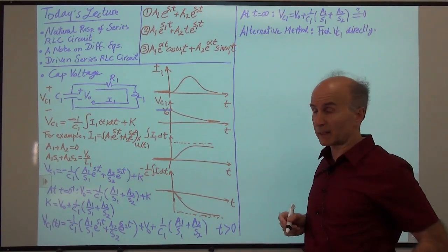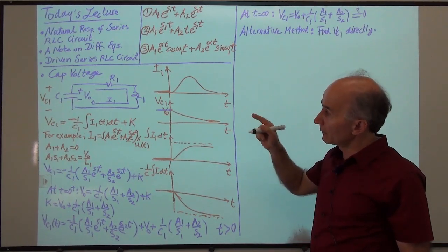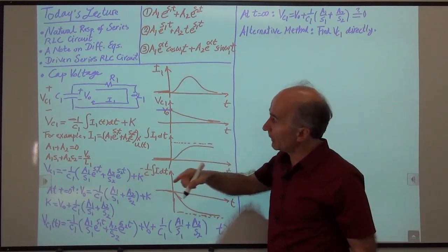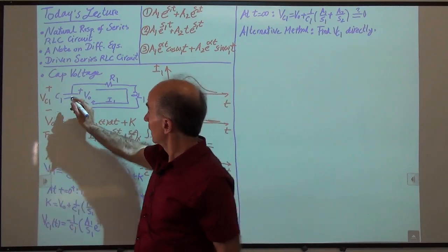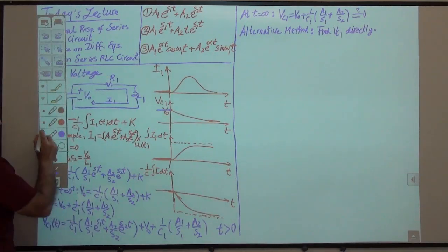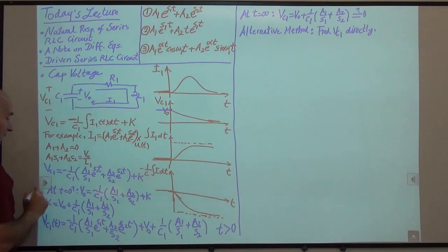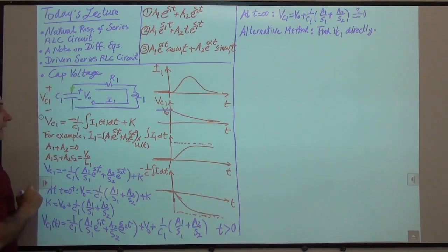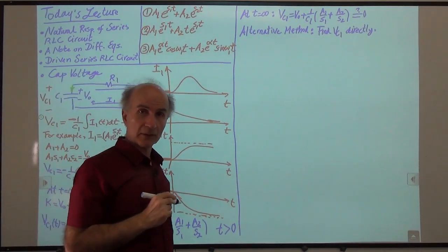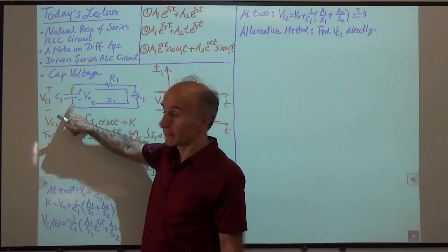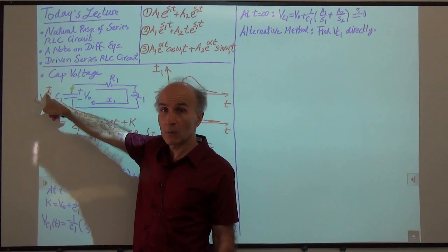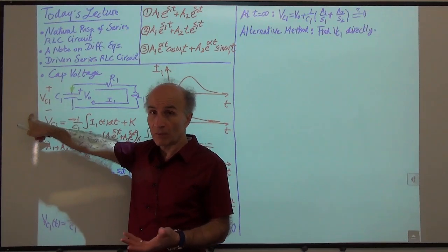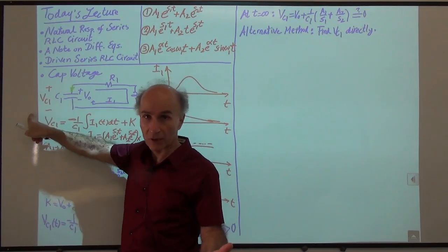All right, so how do we do that exactly? Well, so all of the parameters in the circuit have to be written in terms of Vc1. So how much is the current through C1? This time I have to be careful with my signs, so let's go ahead and change the color. Let's pick the current through C1 like this. Is that okay? So the question is, how much is that current? Well, the current is going from top to bottom, going from the high end of Vc1 to the low end. So it will be just C1 dVc1 over dt, just a standard capacitor equation.